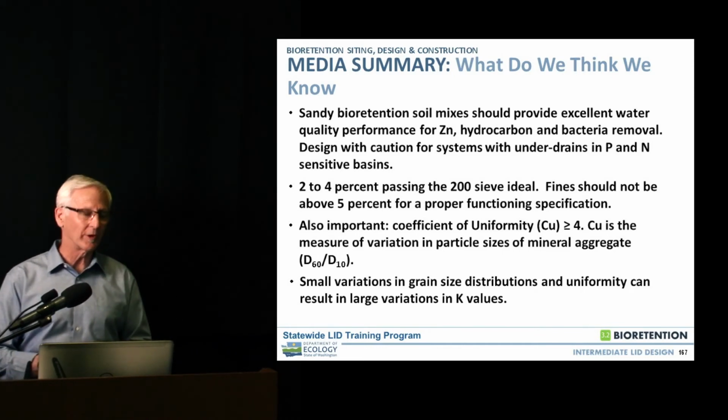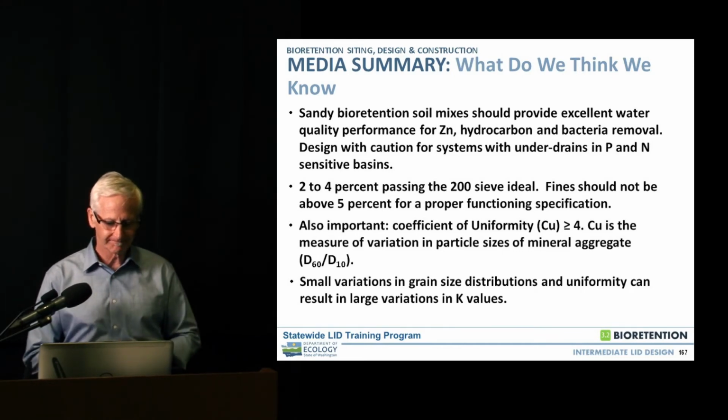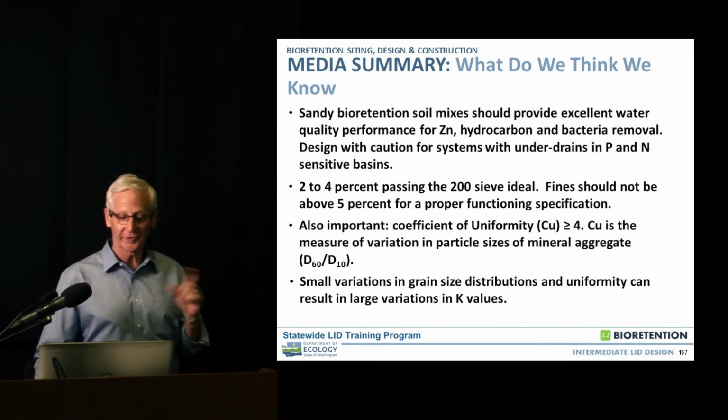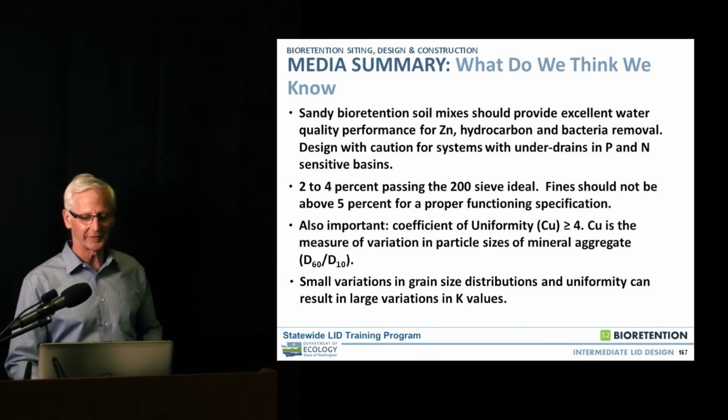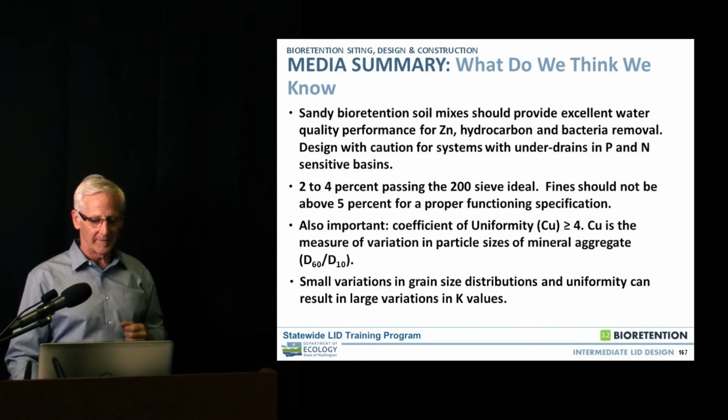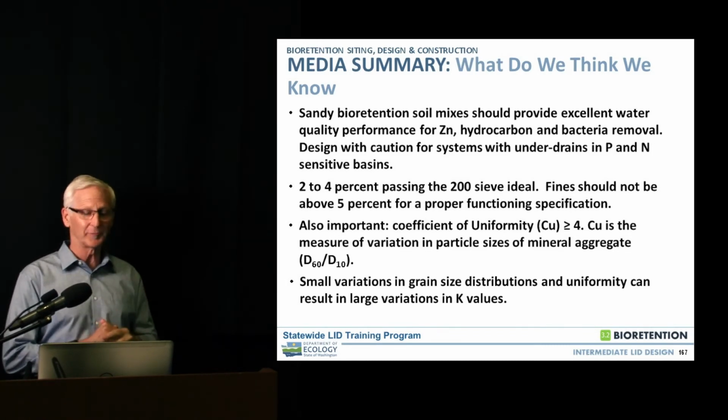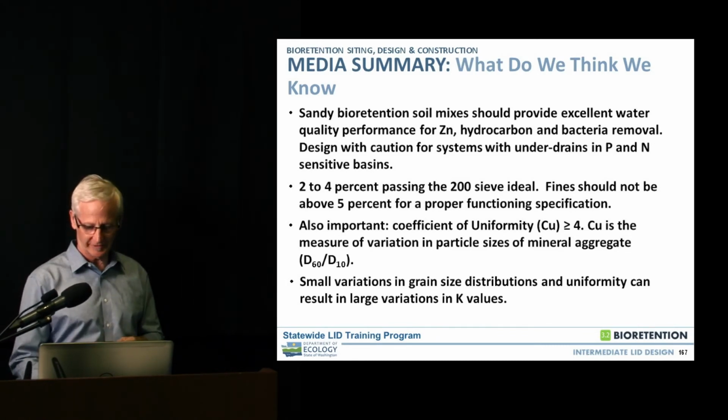Coefficient of uniformity is important, but not a strict criterion. But the particle size distribution is important as far as how this stuff drains. And small variations in these things make a big difference. It really changes how the system behaves, or the media behaves.